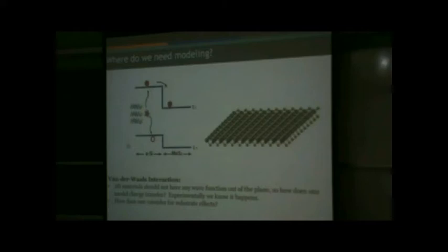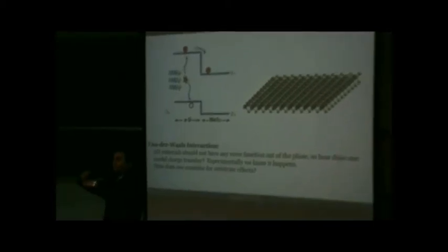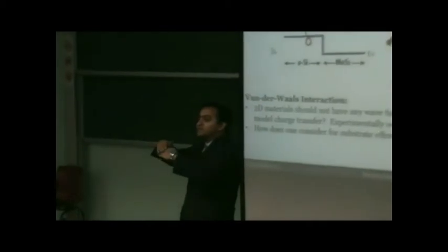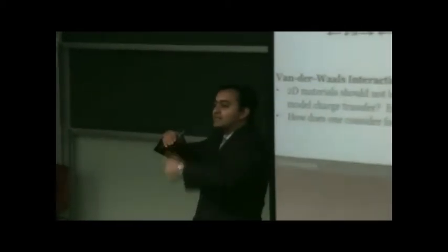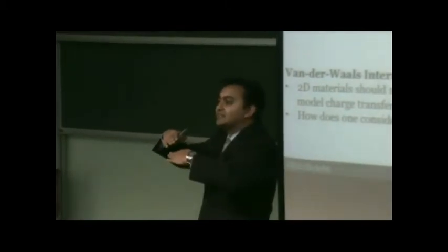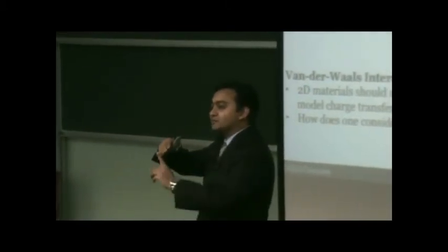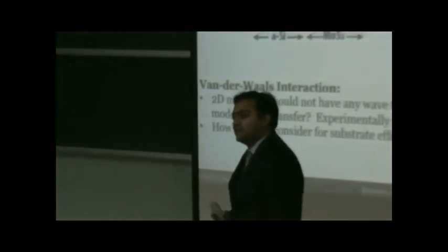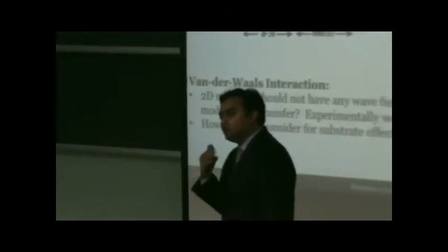Suman was pointing to making tunnel FETs with 2D materials. Very naively, that seems to be what you should never do, because you are putting two 2D materials one on top of the other. All the mobility, all the good properties are in plane. Out of plane, if I do a naive DFT calculation, I see that the band structure is flat. There should not be any electron going out of plane. But we have made this heterostructure. Other people are making heterostructures. They are seeing diode-like behavior. It works. So good DFT theorists probably know the answer, but we don't know.